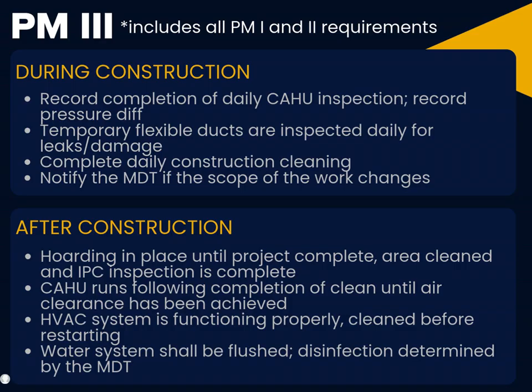After construction, the hoarding stays in place until the project is fully finished and the area has been thoroughly cleaned and inspected. The CAHU continues to run until air clearance is achieved. The constructor performs a post-construction clean. IP&C inspects the area to approve hoarding removal. Hoarding is never removed before inspection.